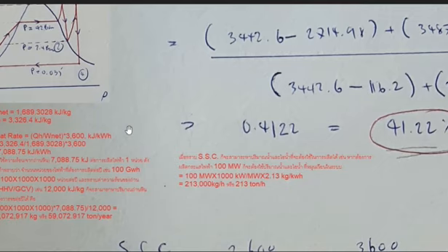That is very important, because we will use that number to determine how much coal we need to supply to the power plant, for example. So the formula for heat rate is QH divided by work net multiplied by 3600.